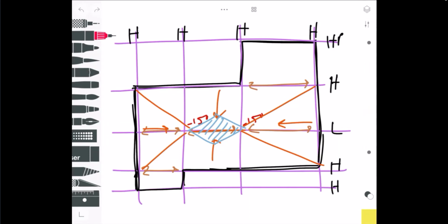Because if the beams are going this way, your joists are running this way, and there's only one beam running across here, you certainly don't want to lower that side of the beam. You could make a low point over here, let's say on the left, but you don't want water concentrating near your parapet edge. That's the weakest point of your building for water to get in over time. So let's stay away from that. The idea is to get the water away from the parapet.